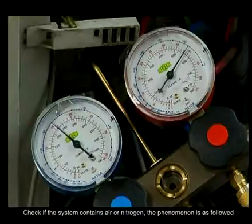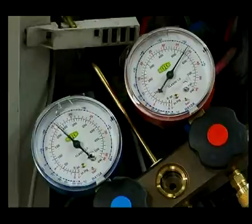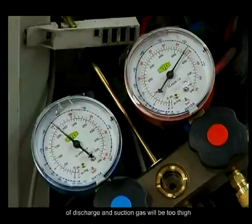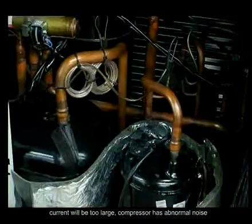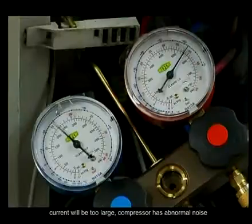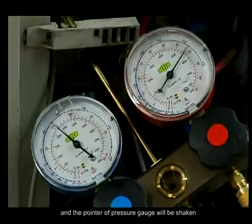Check if the system contains air or nitrogen. The phenomenon is as follows. When it is running, pressure and temperature of discharge and suction gas will be too high. Current will be too large. Compressor has abnormal noise, and the pointer of the pressure gauge will shake.